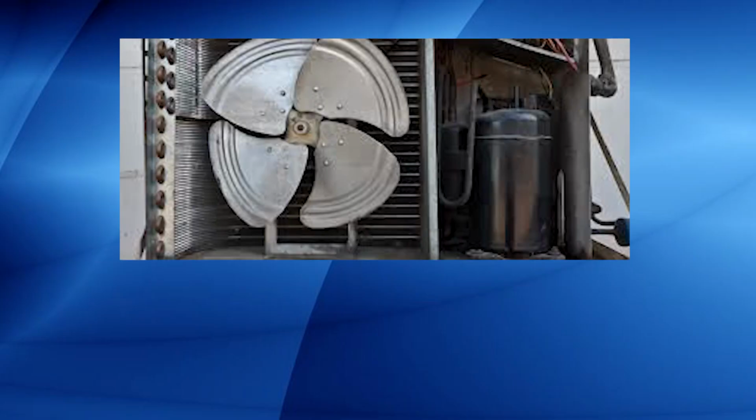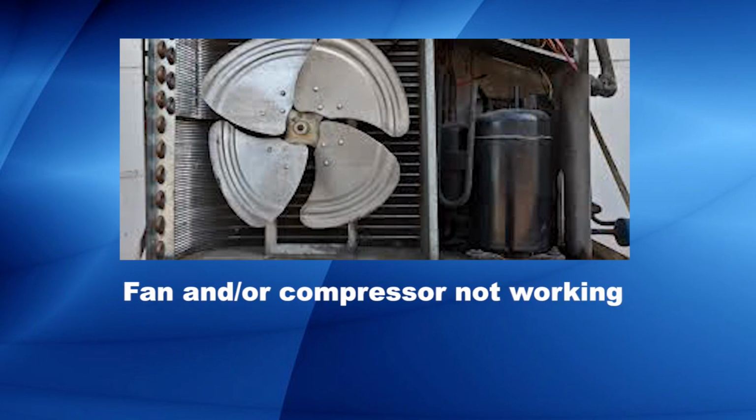The next defect is the fan or the compressor not working. When both the compressor and the fan are not working, the problem is most likely in the electrical circuit.